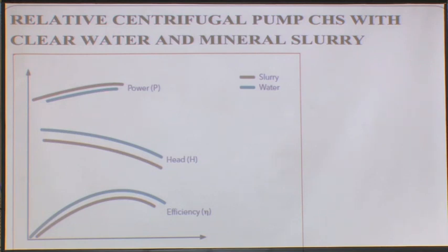So that means it is very interesting, very important that slurry head and water head are not identical. Slurry head and water head are not identical. All the pump testing or all the pump curves which you will see in the manufacturer's catalogs are all clear water pump test curves, and your application is a slurry. So, there is a big gap between the two.